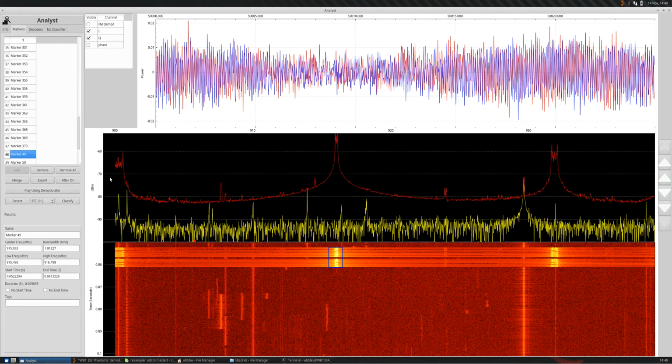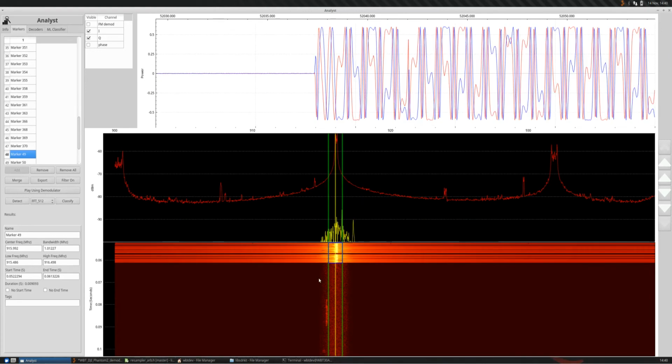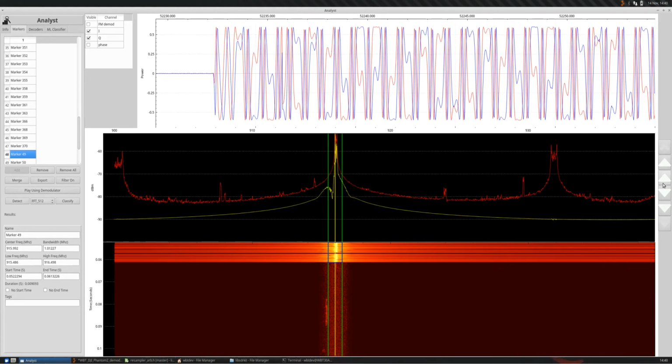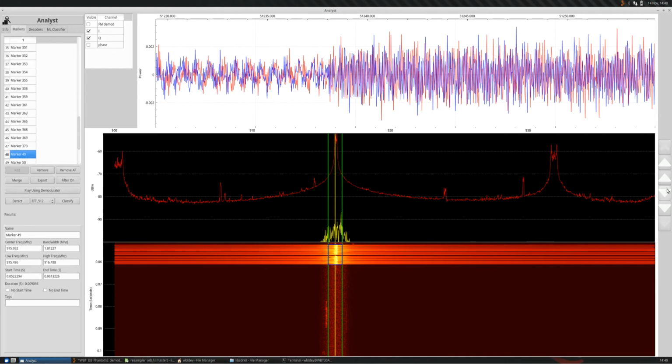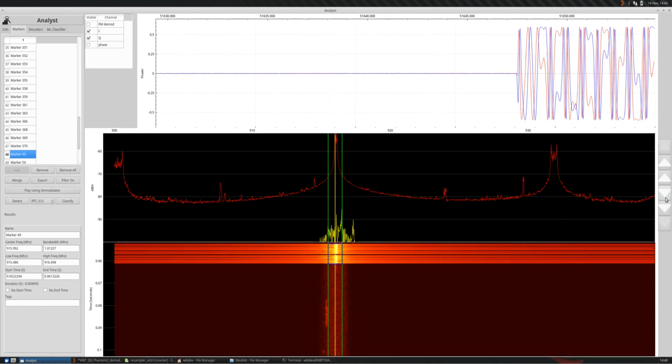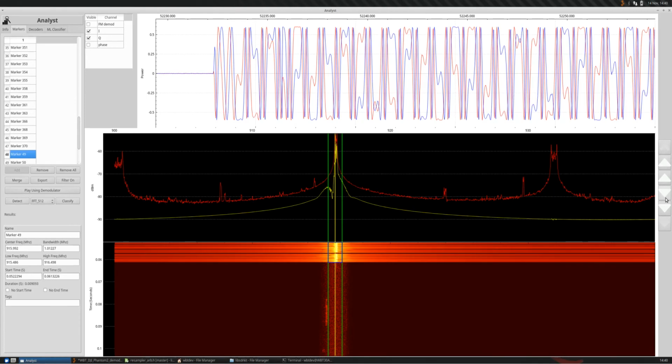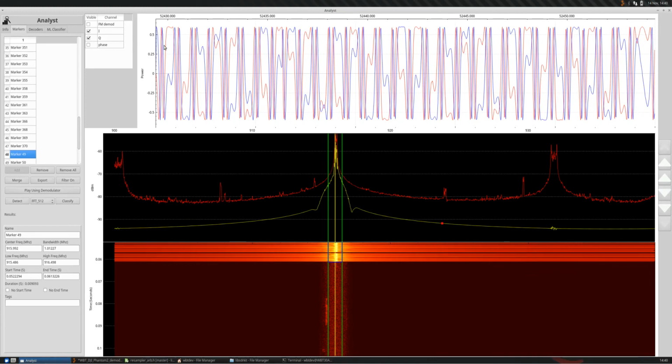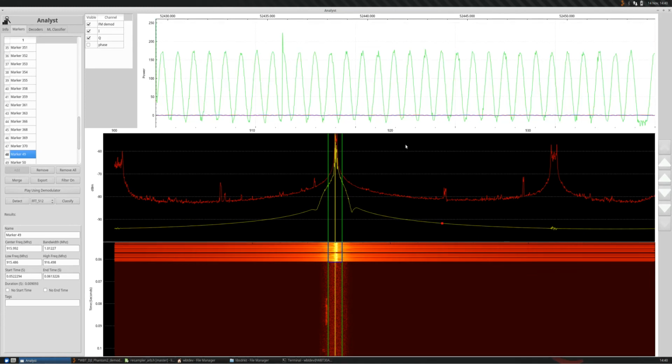So I'm going to click on this marker, and we are going to tell the system to filter only on that one signal and pretty much exclude everything else. As you can see, the noise level here is very low. And if you take a look at the power value of this, you'll see that this is a pretty powerful signal coming up. It's greater than 0.5 and negative 0.5 here in the y-axis. Just taking a look, you can see that this pulse right here is pretty powerful. We can FM demodulate it and see that it's actually a data signal.